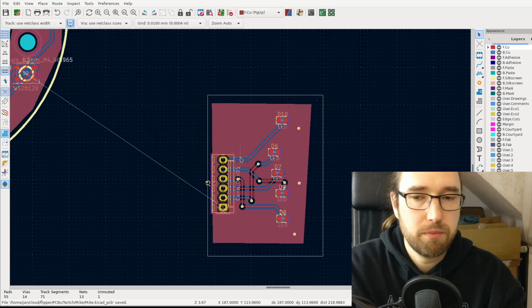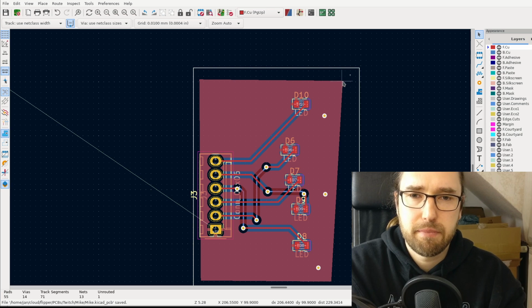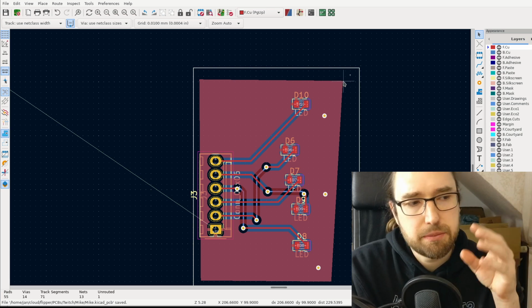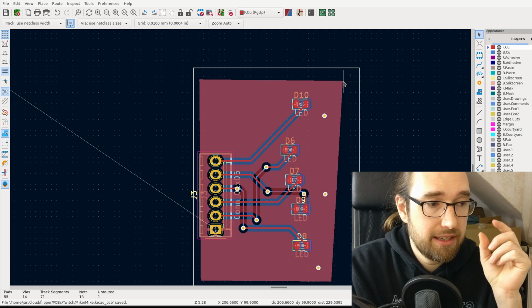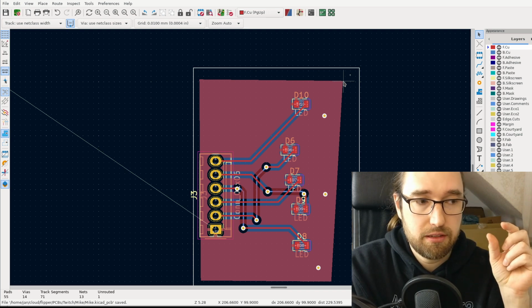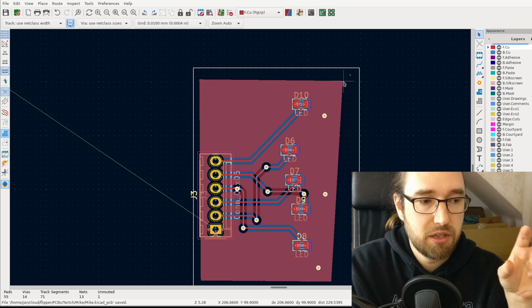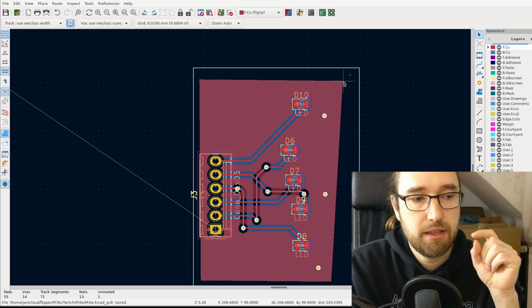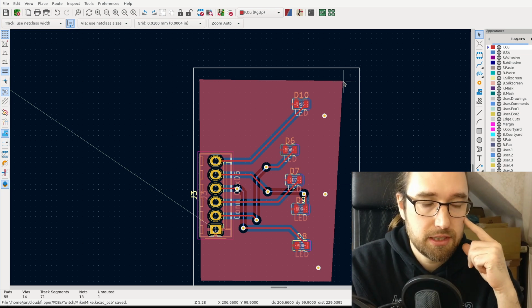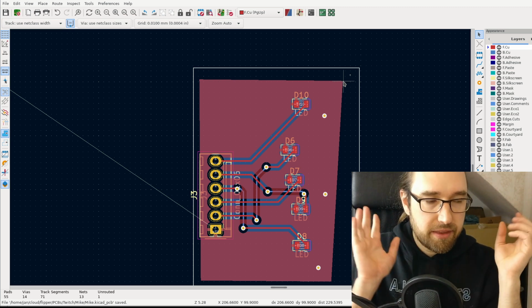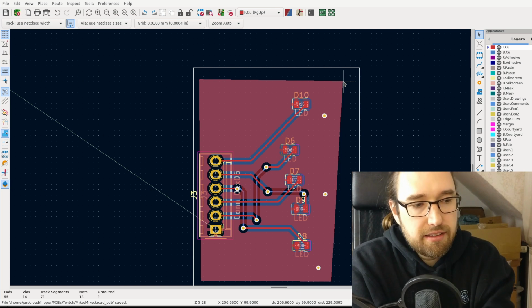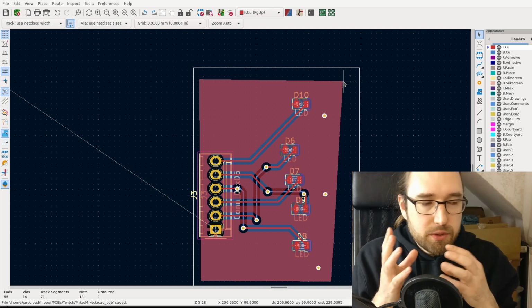And then you got a logo. That's also something to think about if you ever want to export boards. It's important to have some name on it, and ideally some logo, some company name, product name and a version number, because otherwise customs thinks it's something counterfeit, since they cannot relate this board to any documents.